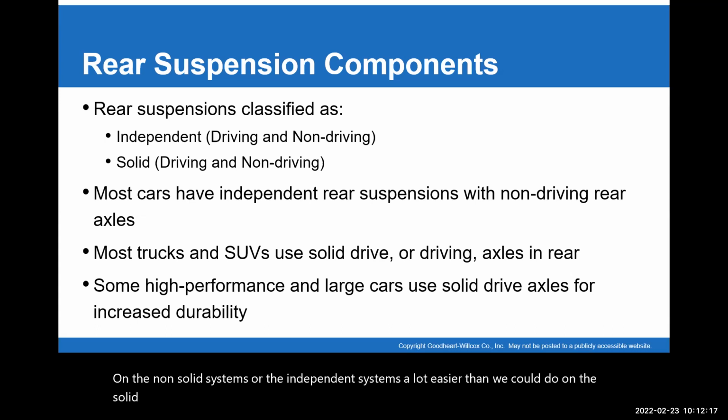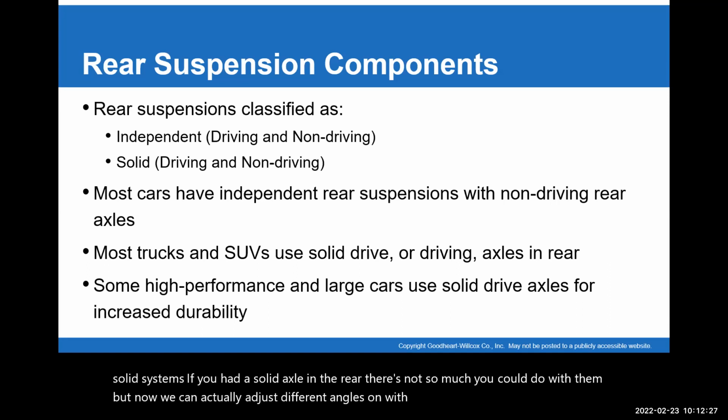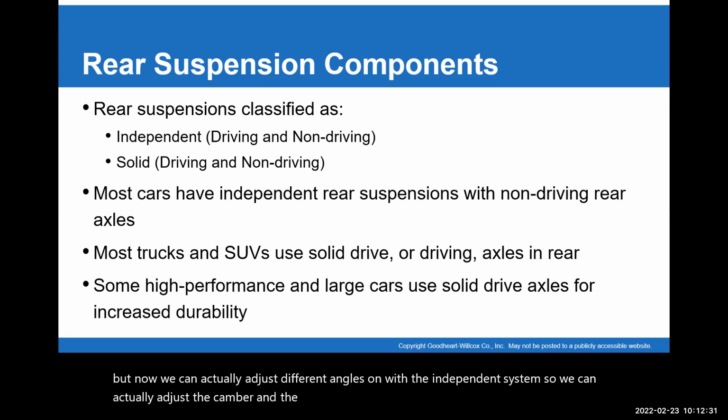If you had a solid axle on the rear, there's not so much you could do with them, but now we can actually adjust different angles with the independent systems. We can actually adjust the camber and the caster. Camber, I shouldn't say caster, but the actual camber and the toe. That's what I meant to say.